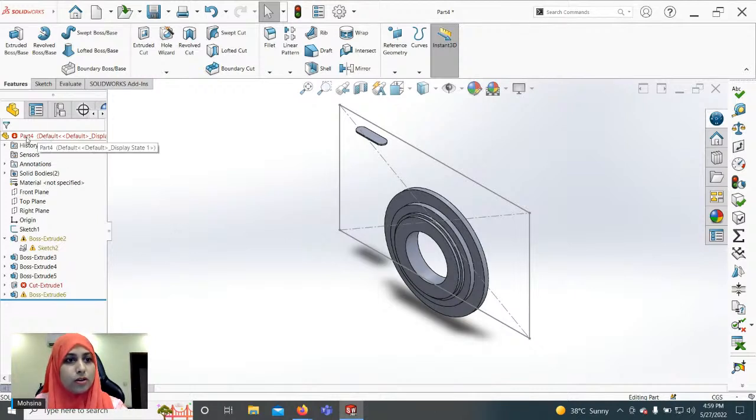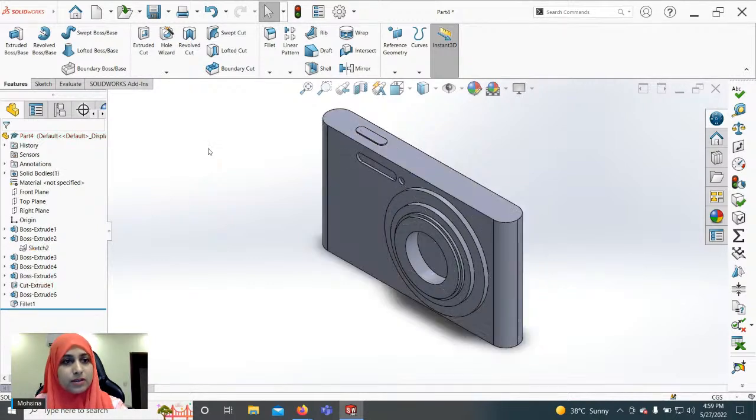And the model also is in red, which shows that it is not correct. So let's press Ctrl Z and we are back to the model. So you can see how dynamic reference visualization has helped us understand how deleting the feature would affect the things depending on it.